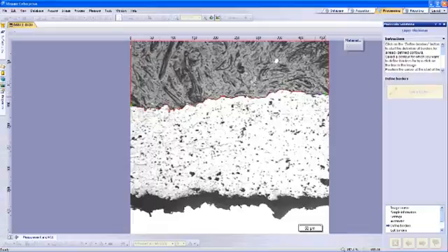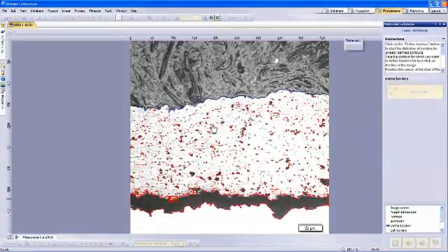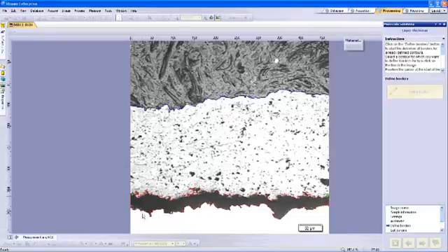Since this line stands alone, we need to right-click to finish marking our points. It will then turn a selected contour line blue. Now we can select the next contour line to define our layer. Select the line at the bottom of the layer which we defined the first contour. Once again, we will mark this contour line with a beginning and end point. Since this contour line was connected with the definition of the dark layer, we can also mark the contour line below with 2 points using the blue cross marks.